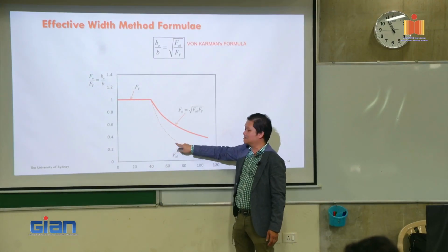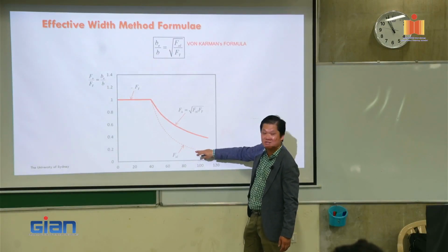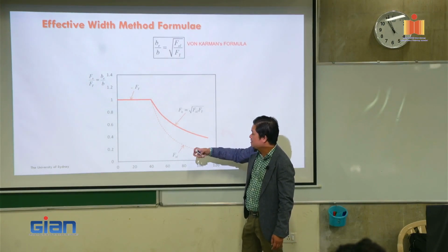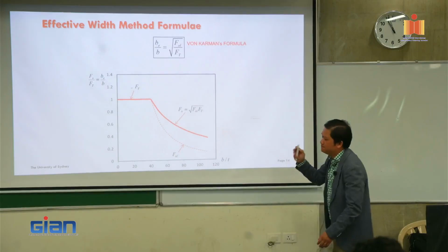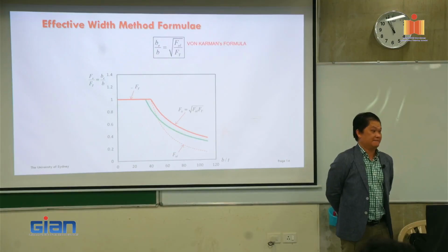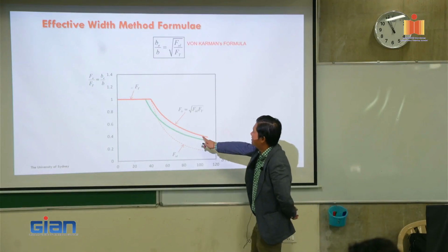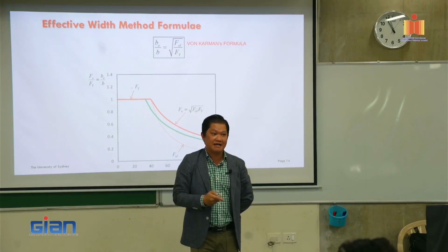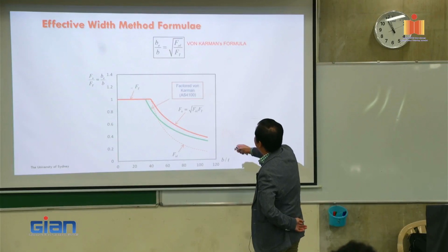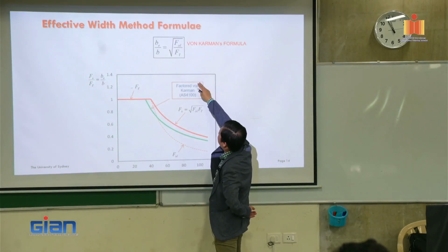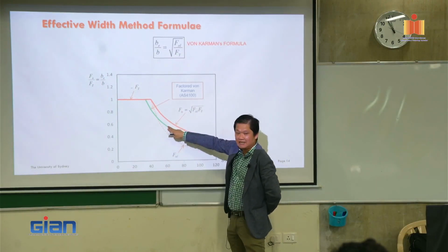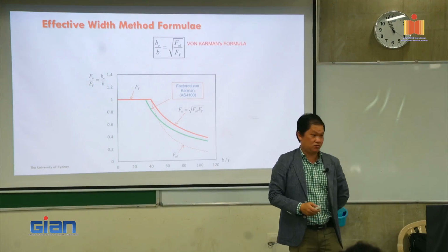So in Australia, sorry, this is the buckling curve, right? The elastic buckling, this is all one. You can see from here to here, it's post-buckling. The capacity goes up here because of the post-buckling. As I mentioned before, because of the imperfection and the residual stress, we need to adjust that. So the green curve here is the equation in AS 4100 for hot roll steel design. It's very simple: they take von Karman and factor it down. So that is the equation that you can find in the Australian standard for hot roll steel, AS 4100.